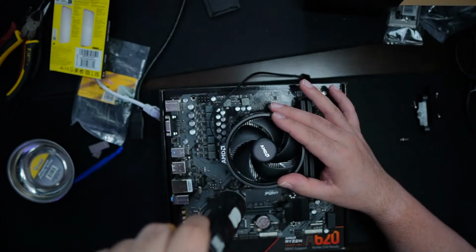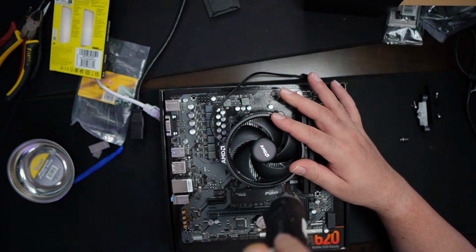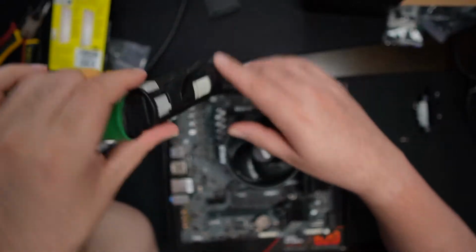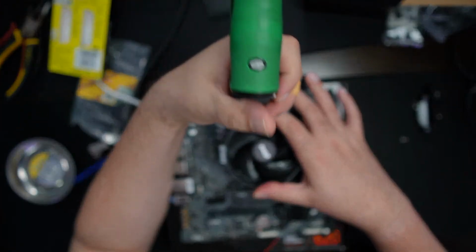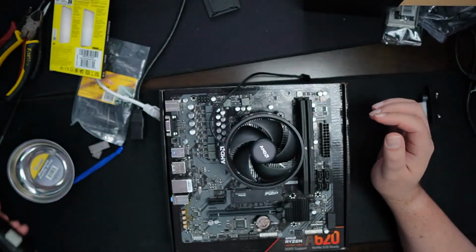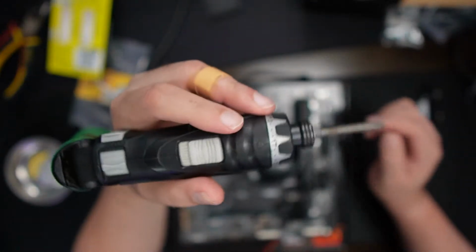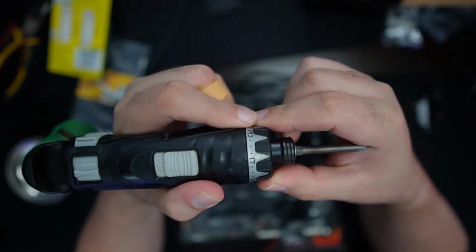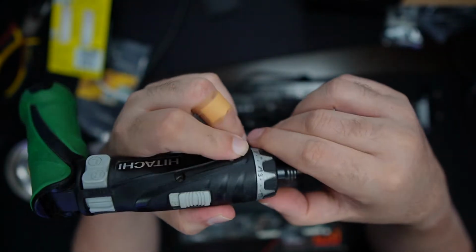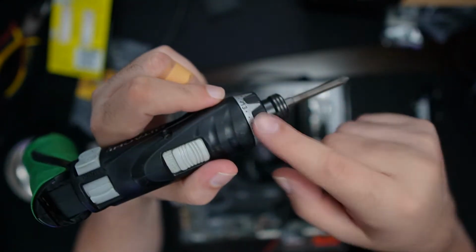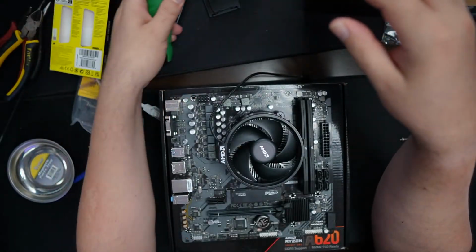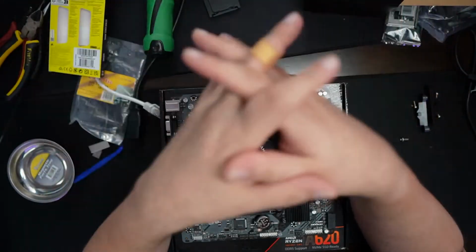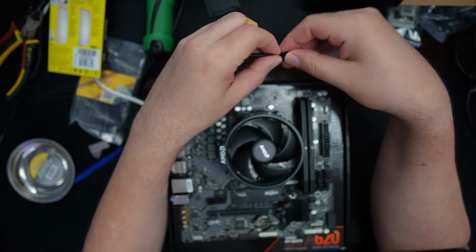Now you can go and actually bottom it out. Again, going the same direction as we were going before to kind of give even pressure all the way around. You'll also notice that when I'm using this, if you're using a regular screwdriver, you just tighten it down until it doesn't turn anymore and you don't break it. I'm on 17 on this. It obviously allows a kickback to make sure that it doesn't go over that type of pressure or torque. So you don't want to over torque this. You want it to go to a certain percentage.